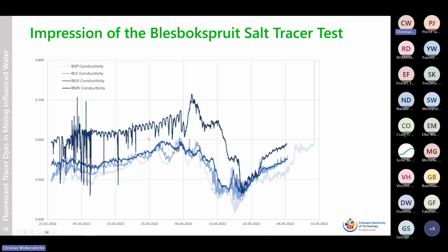What you can see is that you cannot see much. That's a problem that we had there in the stream. The fluctuation of the stream electrical conductivity was in the range of what we wanted to see. So that's the peak that we are interested in. You can clearly see before the peak arrives, the electrical conductivity goes down. The reason for that is ion exchange. So calcium and sodium are exchanged. Therefore, the electrical conductivity first goes down and then it goes up again. So that's the peak at the closest injection location.